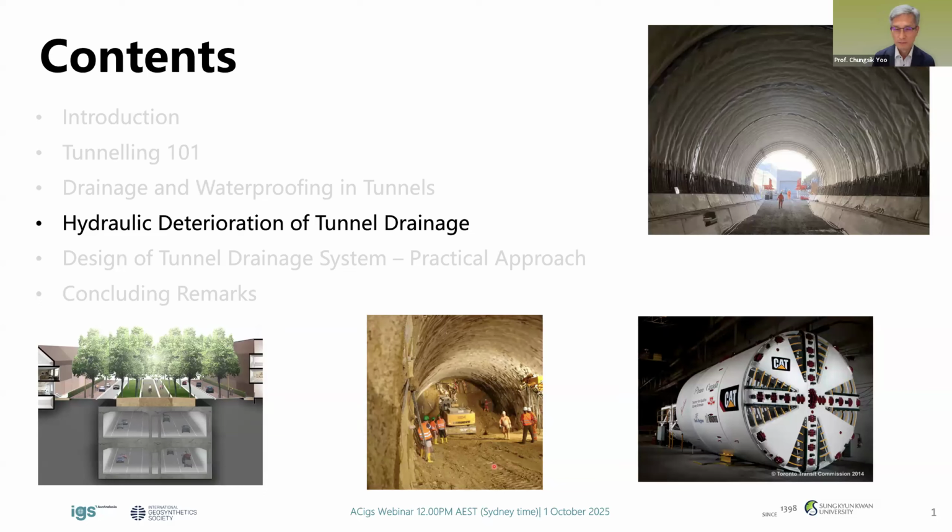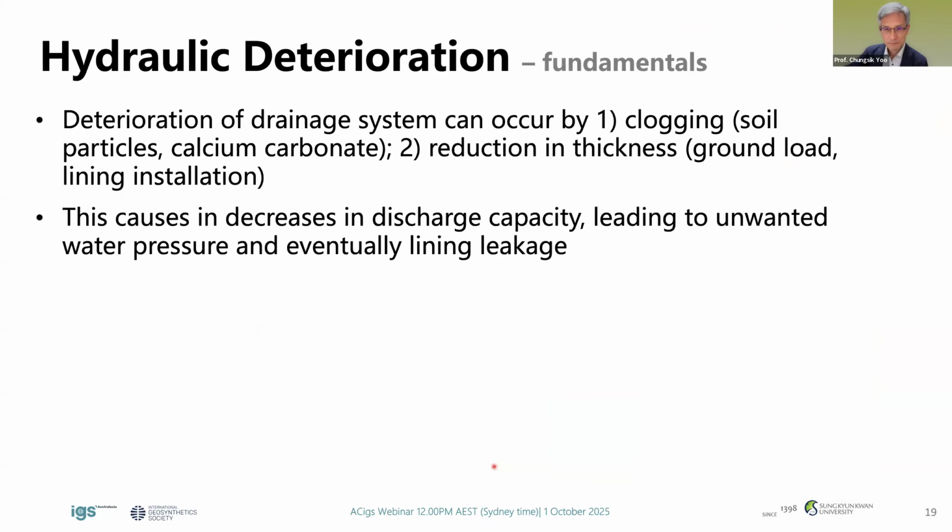So I will talk about this issue under the title Hydraulic Deterioration of Tunnel Drainage. Hydraulic deterioration can occur for two reasons: clogging and reduction in thickness.